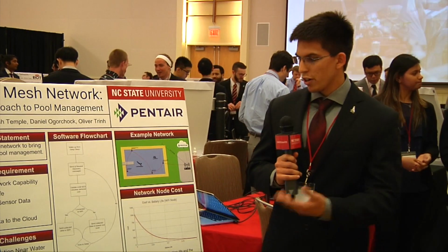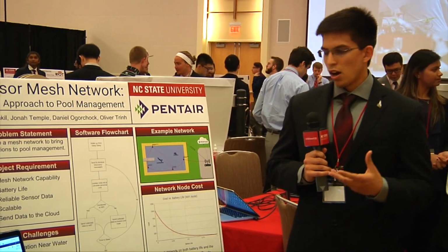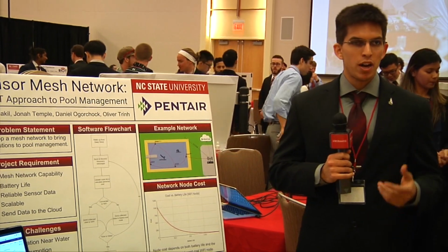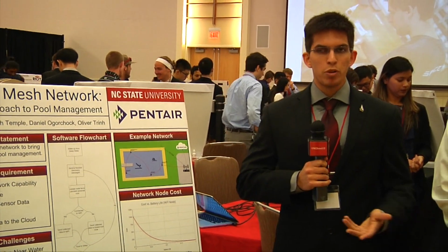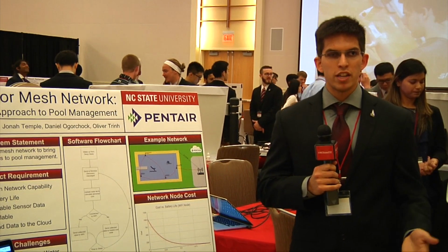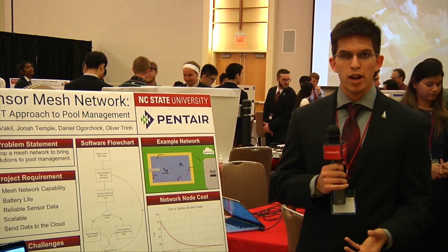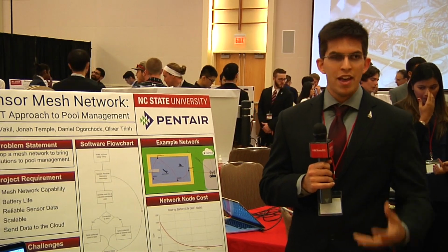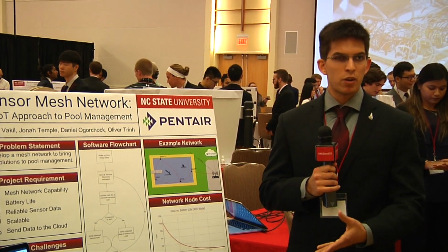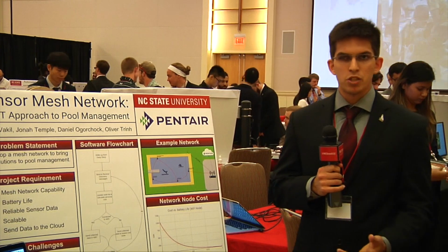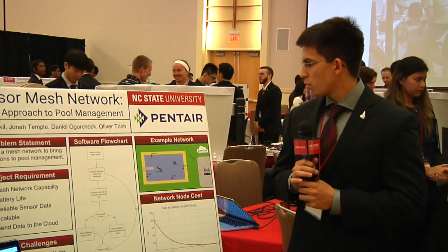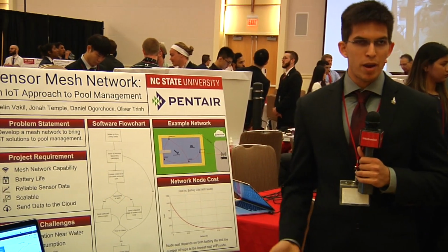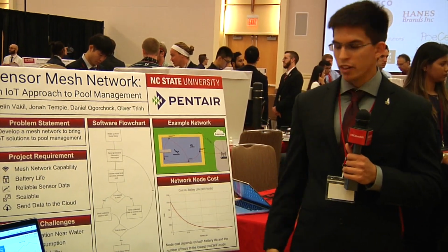Okay. So what our product actually does is once the user buys it from the store or gets it, they'll open it up, press a button. That button will put it into a configuration mode, which then the user will be able to connect to the device directly, load a web page, input their Wi-Fi credentials, and then that node will know, okay, this is the network that I want to connect to. This is the network I should be looking for. Then we have periodic deep sleeps in order to conserve battery and aim for that 1 month battery life.